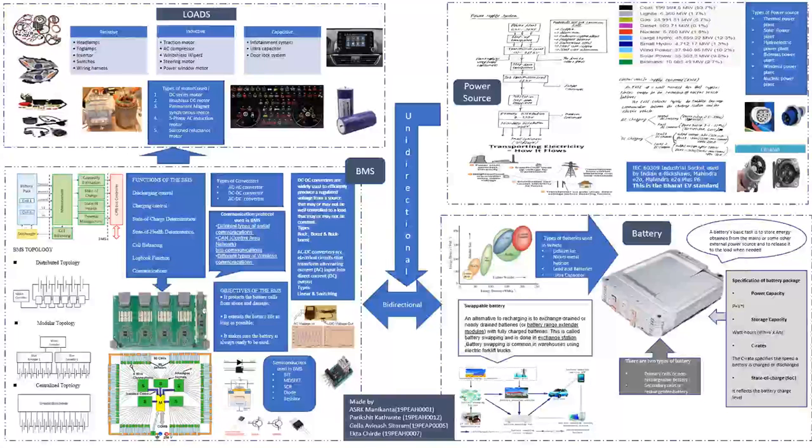Now the state of health and state of charge. So state of health, firstly, three main state of health indicators of a battery are capacity, that is the ability to store the energy. Then internal resistance, that means the capability to deliver the current. Then self discharge, reflecting mechanical integrity and stress related condition.